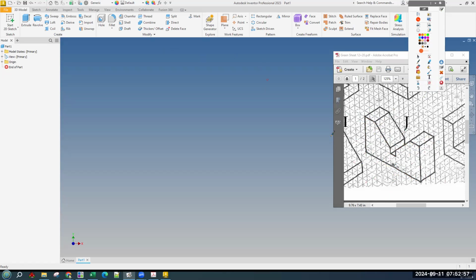The way we're going to do this is with the line tool, which is different than the rectangle tool, even if you make a rectangle out of lines. The reason is the rectangle tool automatically constrains opposite sides to the same length. It automatically constrains 90 degrees if you make a full rectangle. And you can't undo those things accidentally, which is good. With the line tool, the process is always make the line, dimension the line. Make another line, dimension that line.